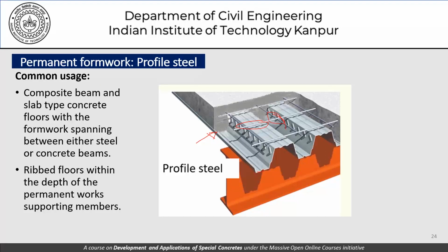So we have this formwork which we don't have to bother to remove. And that's what I said in the beginning of this discussion, that whether or not this formwork should be considered as a part of this structural member in terms of whether or not it provides any flexural rigidity or how it participates in the load carrying mechanism of this slab. That is something which the designers would bother about, and that's something which the designers need to understand better.